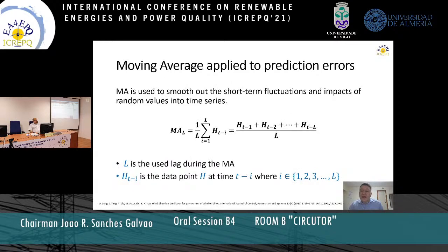Observing the data, we know that several variables make the data take a sinusoidal behavior, so we cannot clearly see the trend of the data. And then it could be kind of difficult to detect a fault. Moving average appears instead as a strategy to extract the trend of a time series, computing the mean of shorter and successive time series. The presented equation in this slide computes those time series means or averages, in which we must define the temporal window or the lag. For this case, we set 30 minutes as the lag.